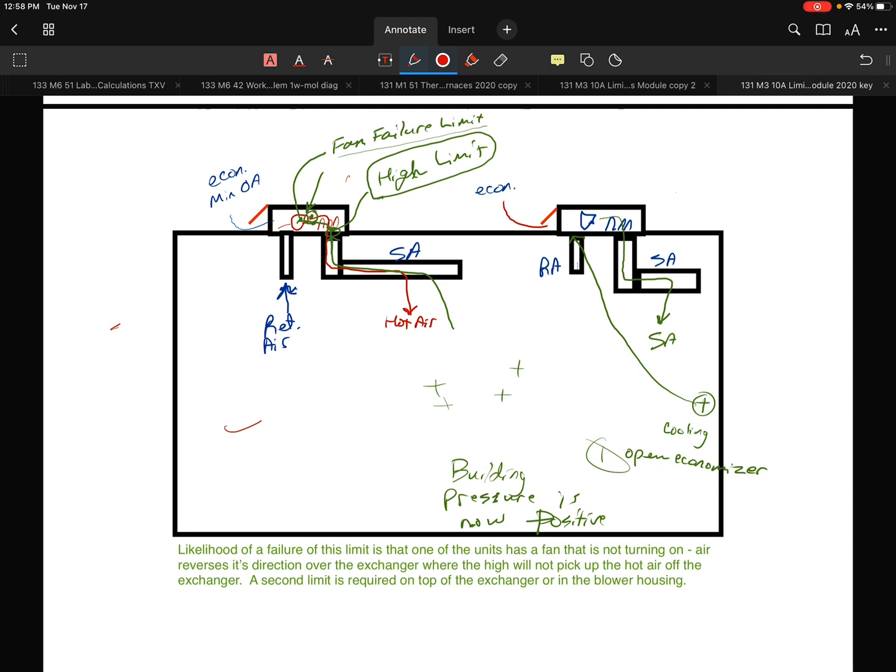On a unit that's operating correctly, you're going to have the economizer open at a minimum position as a general rule, and it's simply going to blow that air right into that space. In a lot of the larger spaces, the rooftops will oftentimes do this. You might have 2, 3, 4 rooftops in a space, and they're doing it to spread out the demand. Rather than put one big giant unit, they'll put a bunch of smaller units in there. They might set it up where one thermostat goes to several units. They don't have to, but that could be a possibility. So if they've got a rooftop that's blowing warm air in that space, again, we're talking minimum air for ventilation.